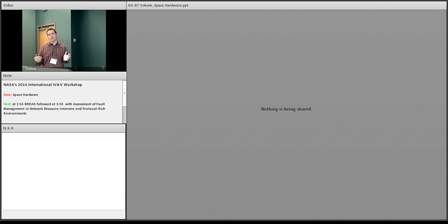Now, that really doesn't matter a lot of times if you're the master clock and you're simulating every component. So you can run faster than real time, slower than real time, and that's often desirable. Doesn't make a lot of difference. But if you bring in external components like a ground station, let's take Eclipse for example, we're not controlling Eclipse's clock. So if it's sending up a command and it's expecting back a response in 2 seconds, and we're running 4 seconds below real time, the whole thing's broke right there. So those are cases where we have to get this thing up to real time to get it to work as a full integrated system.